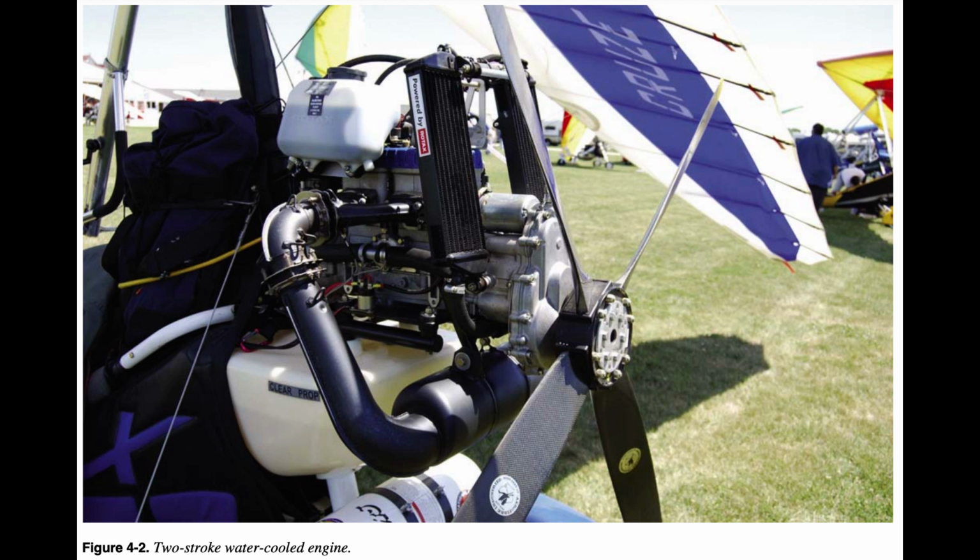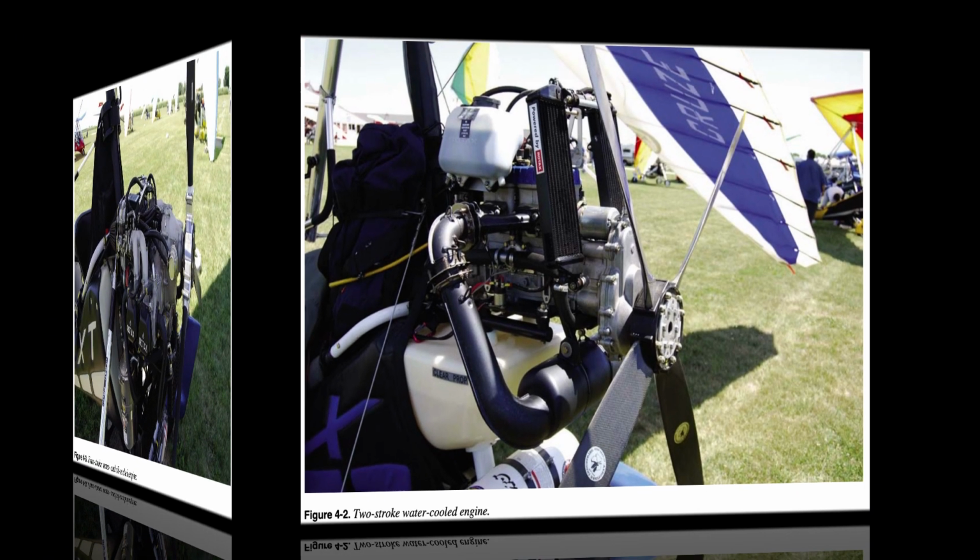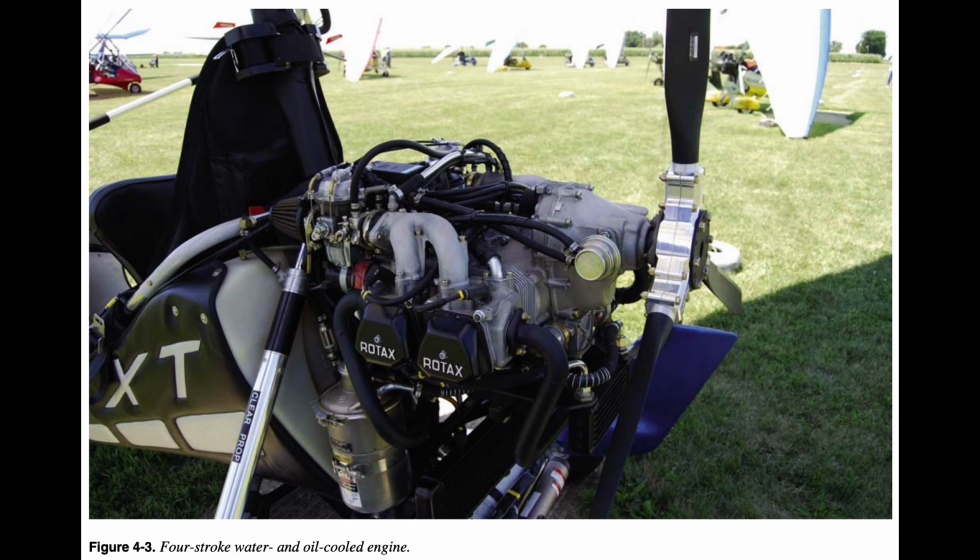Two-stroke engines require that oil be mixed into the fuel to lubricate the engine, instead of being held in a sump and requiring a separate pressurized recirculating system like that of a four-stroke engine. Details on two-stroke oil mixing are covered in the lubrication section. One stroke, as the piston moves up, is intake and compression, while the second stroke, as the piston moves down, is power and exhaust. The two-stroke engine performs the same functions as a four-stroke engine in half the number of strokes. End of page 4-2.